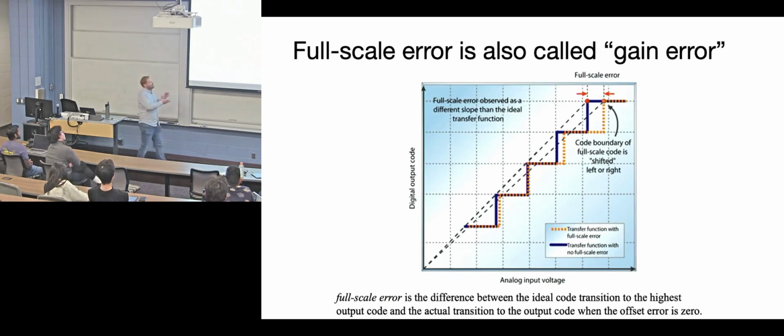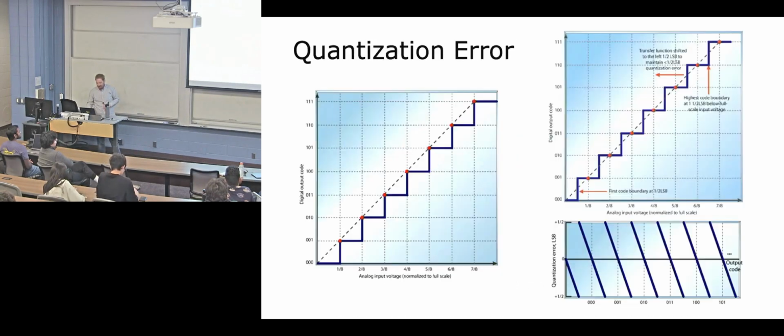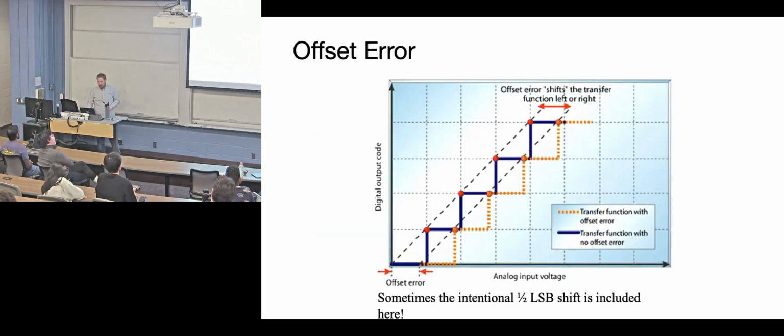There are other errors called full-scale error or gain error, which means there's a consistent gain aspect, so that in this particular example, the higher the value is, the more error. If it's nice and linear, that's just an equation you have to apply to compensate for that amount of error. So all these three are just acceptable, like this is just your design, you just have to accept it. These are recoverable, you can measure them.